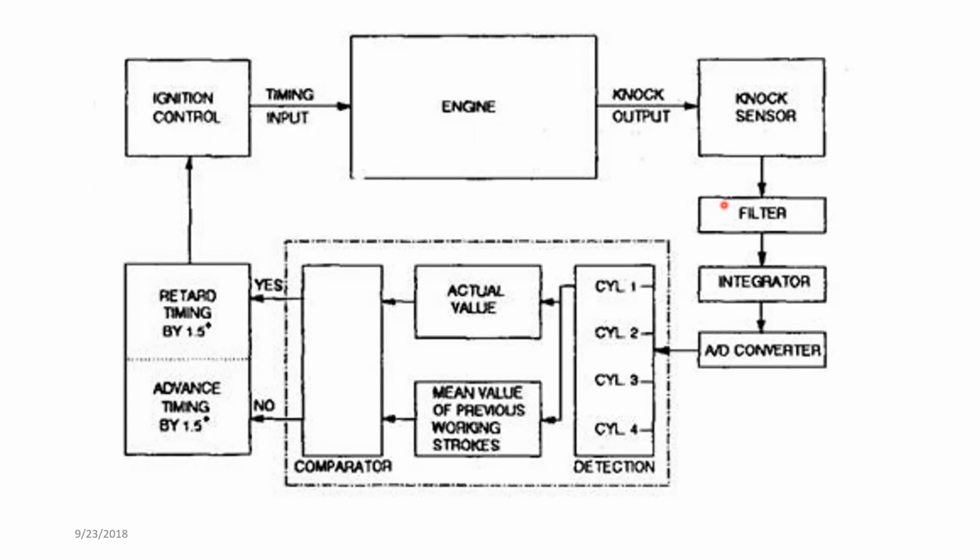The engine always tries to advance the ignition, but if it measures a knock output, it understands there's knocking because of the previous advancement of the ignition timing. So now it's time to retard the ignition timing back. That's how the system works.